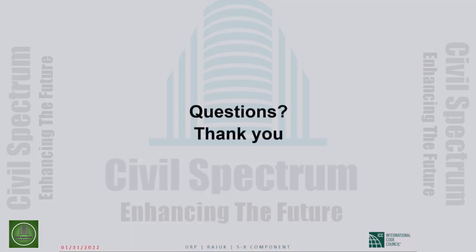Should we consider dead load or self-weight while calculating the story drift for lateral load, like a combination of dead load and earthquake? Yeah, this I addressed more than once. So your concern is interstory drift staying within tolerable limits. So the question is, does it make any difference how much gravity load you have sitting on your frame?